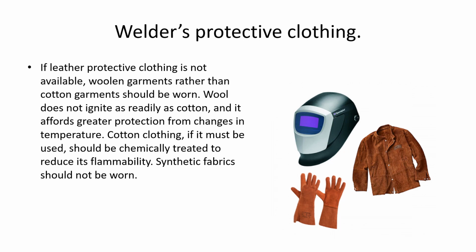Leather's good, wool's good, cotton's good, but you don't want to be wearing polyester or rayon or any of the other man-made synthetic fabrics, because it's just something that's going to catch on fire. So don't be wearing clothing with those types of materials. They're not good for welding situations.